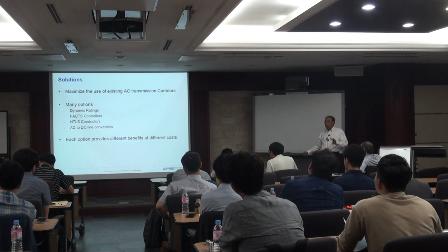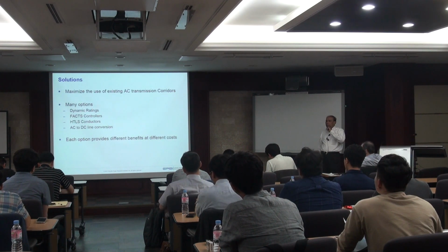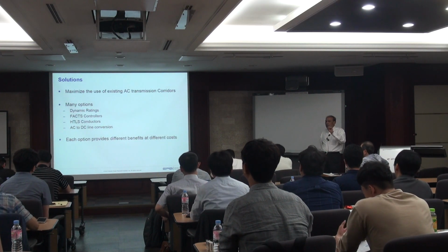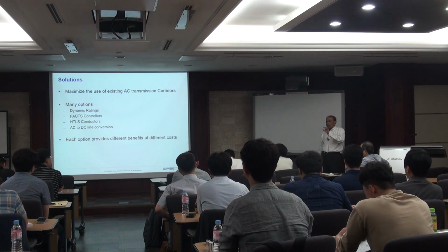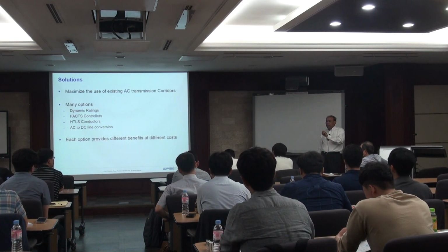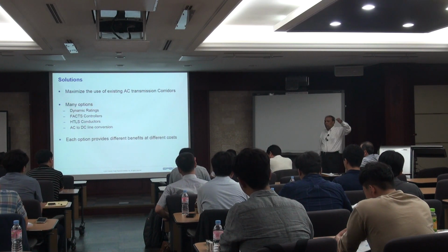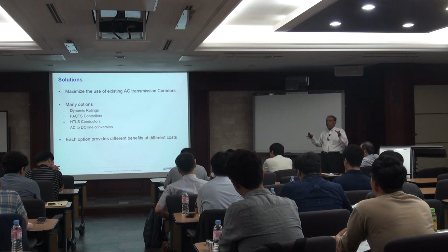That means you don't do anything except monitor the weather, the temperature of the conductor, the sag of the line, or the tension of the line. Temperature, line sag, and tension of the line are all related. You can use either a tension monitor or a video sagometer we developed with a video camera mounted on the pole. So if you monitor those and they are within the limits,